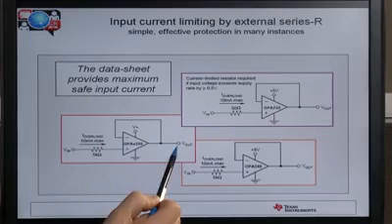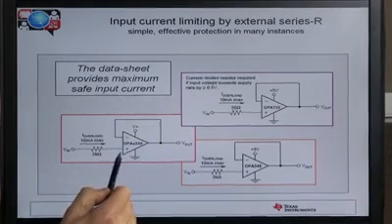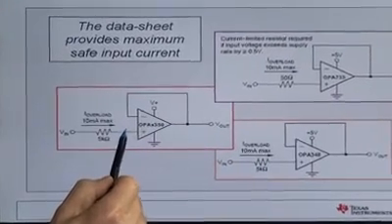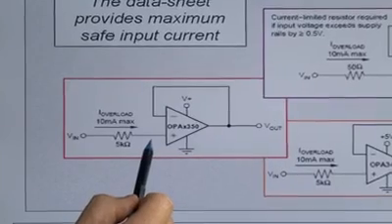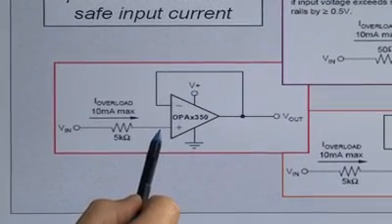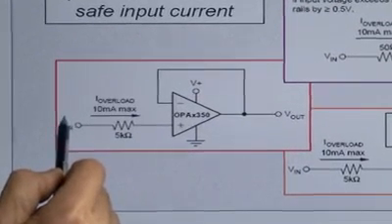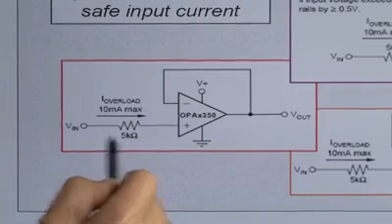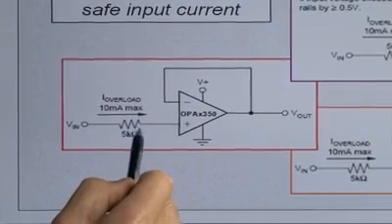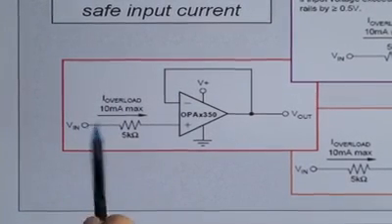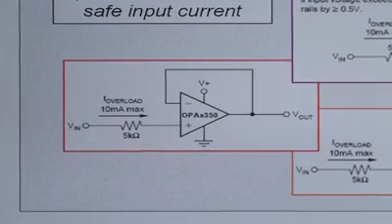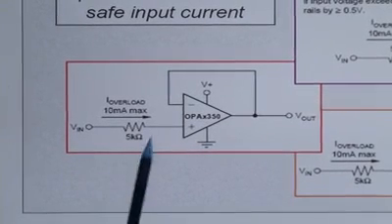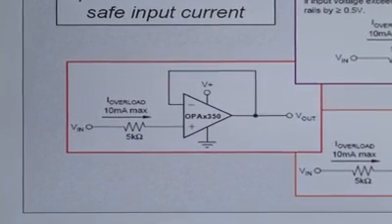If we take that OPA322, for example, with its maximum, let's say we've got the input at 5 volts, so the maximum input voltage was a half a volt above that, or for a total of 5.5 volts. If I put 10.5 volts over here, I want to develop a 5 volt drop across the resistor with 10 milliamperes. And it's simply Ohm's law that dictates what the resistor is. Usually it's just a matter of a few hundred ohms or kiloohms. We've got to be careful not to make that resistor too large because it does add noise to the circuit.